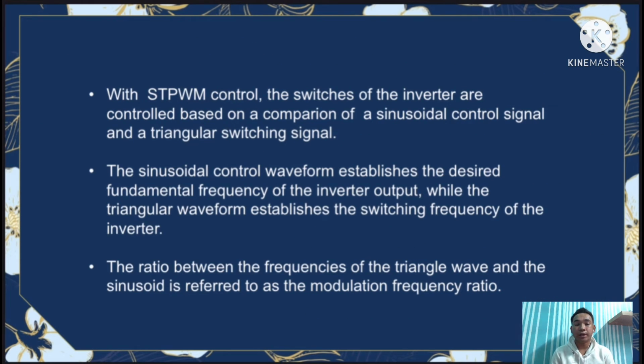With STPWM control, the switches of the inverter are controlled based on a comparison of a sinusoidal control signal and a triangular switching signal.